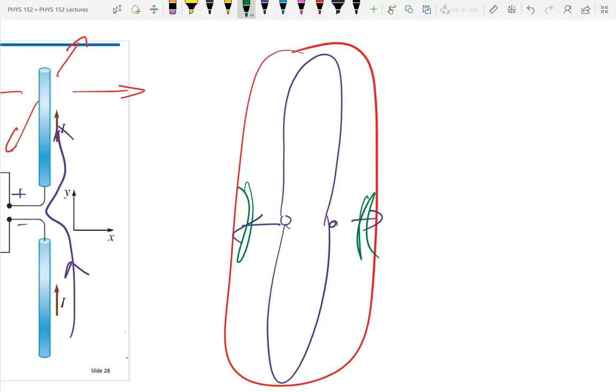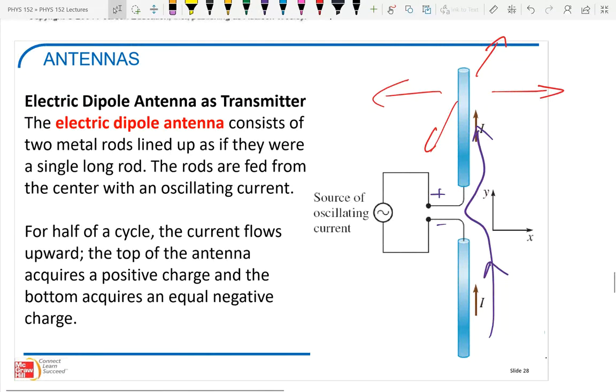And so just like with sound, when we talked about beats, if you have two speakers, as you walk around a room, if they're exactly in phase together, you're going to have places where it's louder and softer. That's what they were doing with their radio signal, to make it so they can be directional about it and not waste energy broadcasting where there's no one to hear it. So that's a simple dipole transmitter.